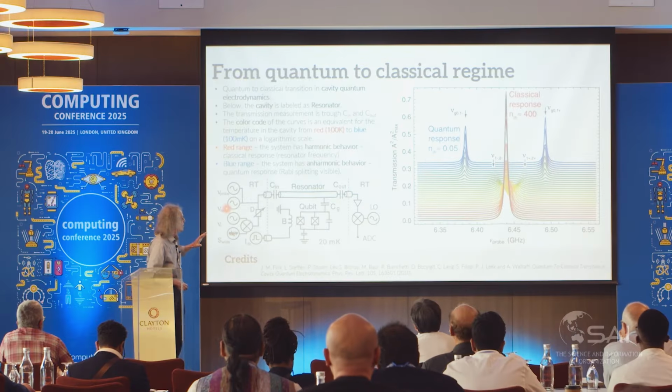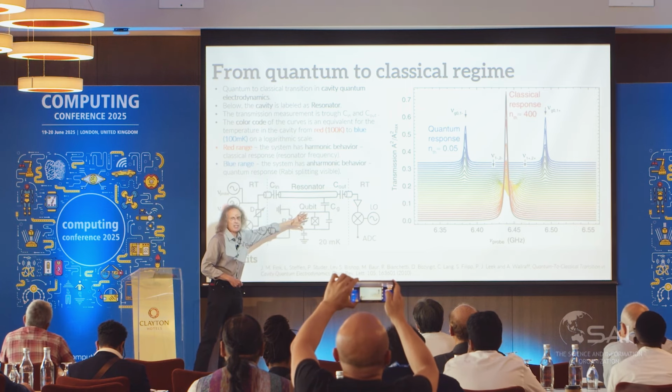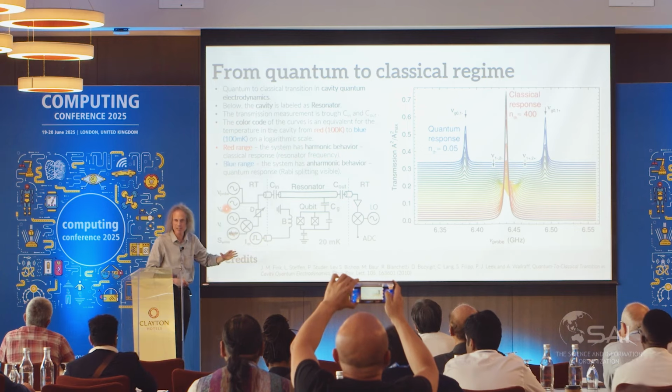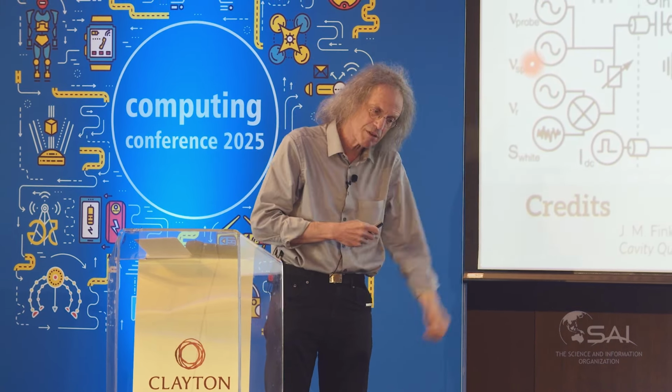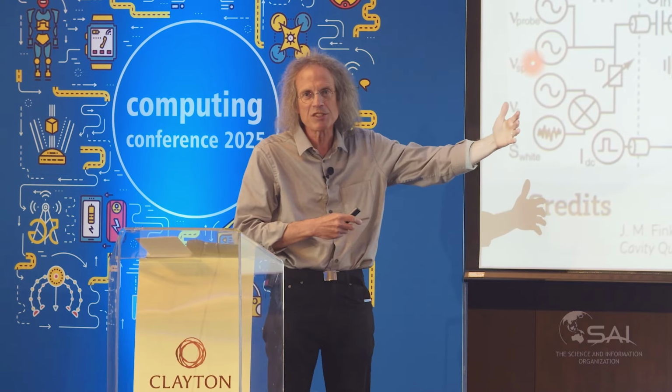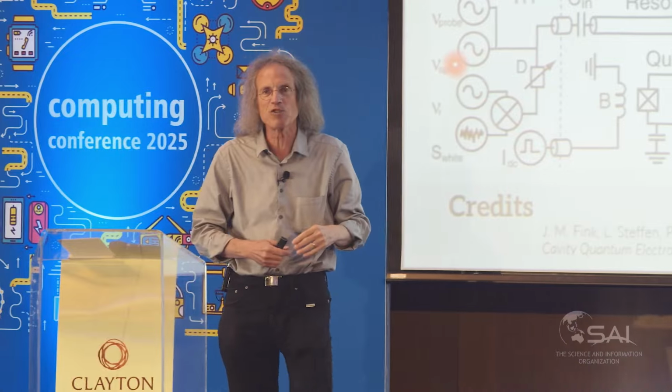Now, to look at such a system, it's very busy, but let's start with this. A transmon qubit is nothing else than an LC resonator. And yeah, it's this pendulum. Now we have a problem because we want to build a qubit that needs two distinguished energy levels. Since everybody knows a resonator just has harmonics, we need to make that non-harmonic. And that's the reason to get the Josephson junction in.